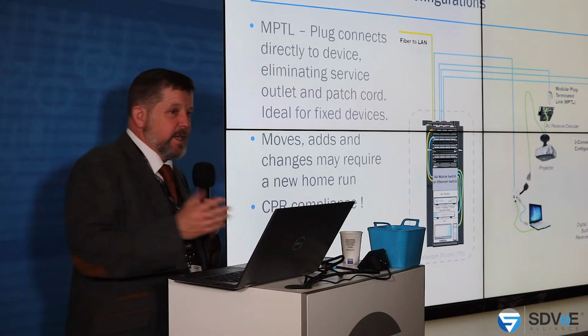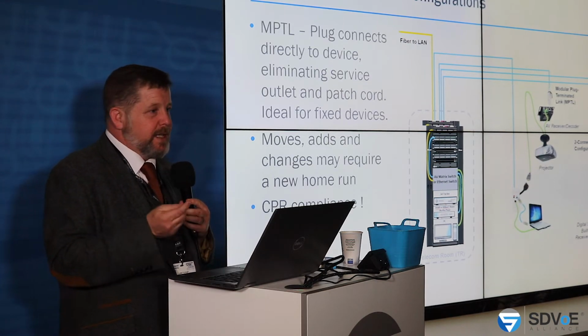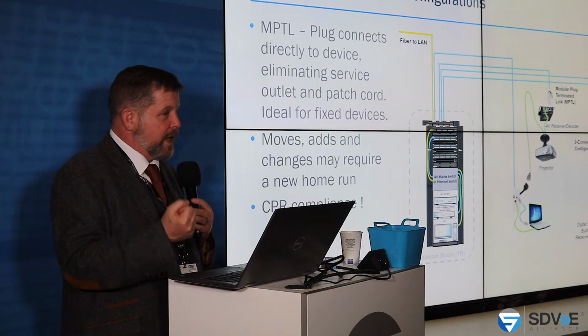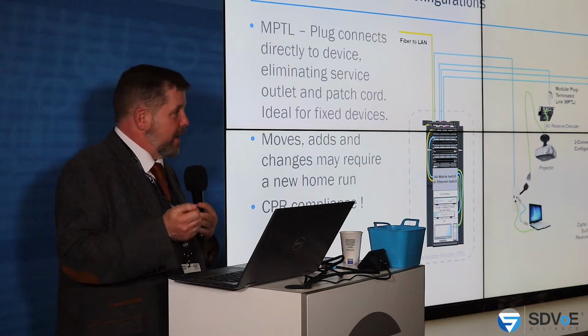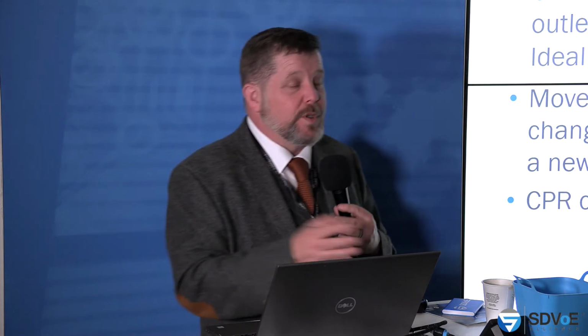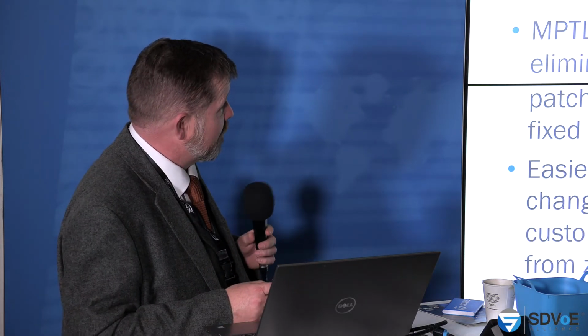Now one of the biggest issues with patch cords, if anybody works with a patch cord, it is typically a stranded cord. It is not a solid cord cable. If we are trying to deliver high definition video over distances of 90 to 100 meters, stranded cord will attenuate the signal more. There is more chance for crosstalk and more delay skew on the cable, which will affect the video transmissions that you're trying to look at.